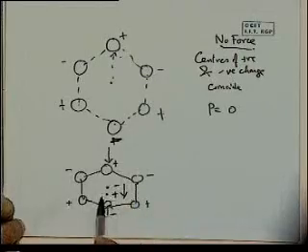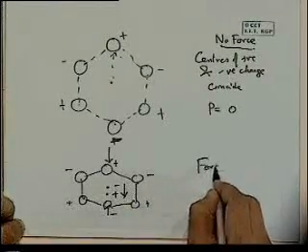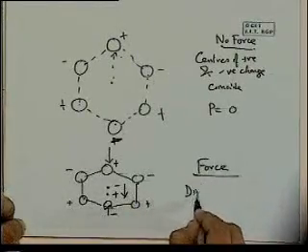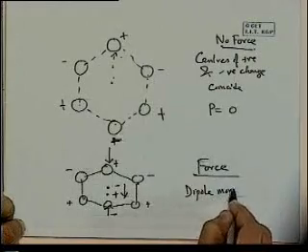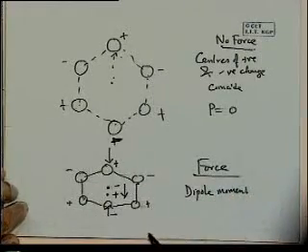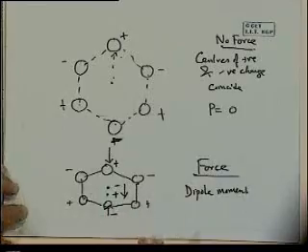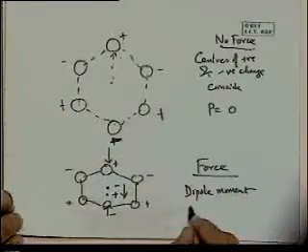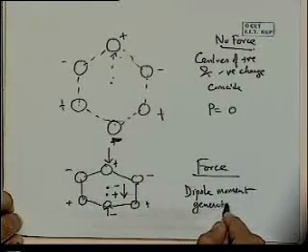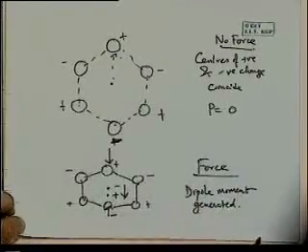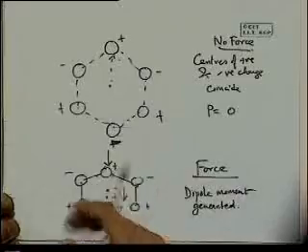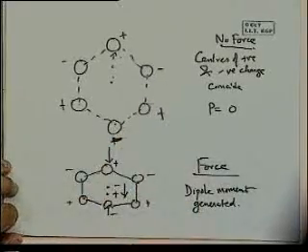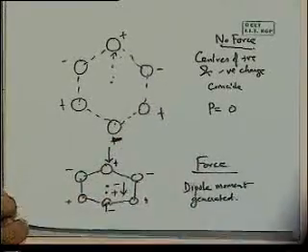Now it turns out, in this particular case, when we applied the force, the dipole moment is generated in the same direction as the applied force. But that's not always true. I apply the force this way, we've got the dipole moment along that same axis. But we can have situations where that will not be true. So in this case, because of its non-centrosymmetric nature, we will get polarization.